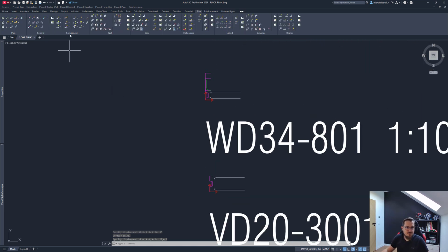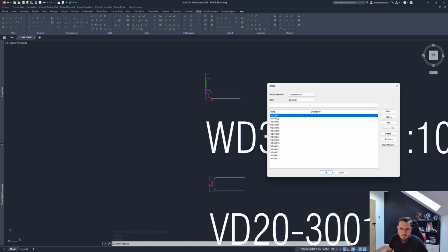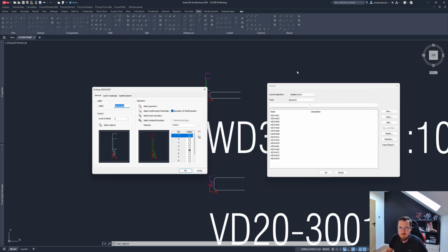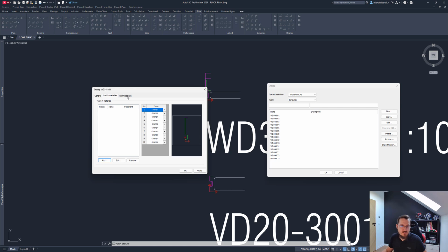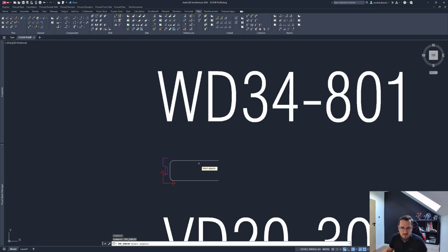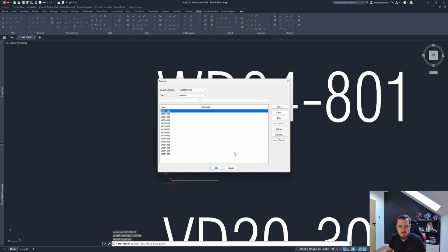Now let's go back to plan and let's edit the end caps, because this is where you actually edit the reinforcement in the end caps. I'll go and open up the first end cap. So that's the 801 end cap, right? And here I have some specification of the geometry of that, the extent of the end cap for the cast-in materials if they are placed automatically, and the reinforcement. So let me select the objects for this particular end cap, 801, and let's select the reinforcement. And the base point, which will be this point. And we get the preview of that. And that's it. I'll just accept that and save that.